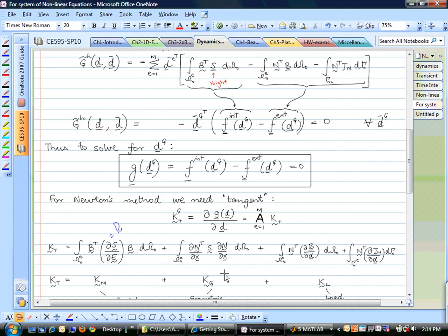If you stand on the rope, that will have a large deformation. If you now stretch the rope and stand on it again, it will not go down that much, right? So the stiffness of that rope depends upon how much internal force it's already carrying or how much deformation it has already had. So that component, this is the P delta effect that people talk about.